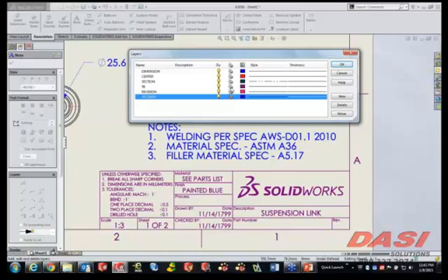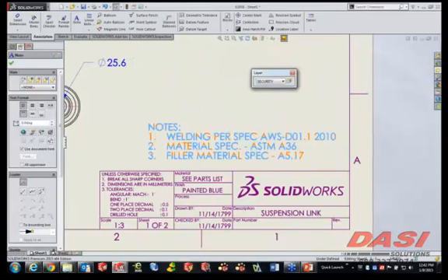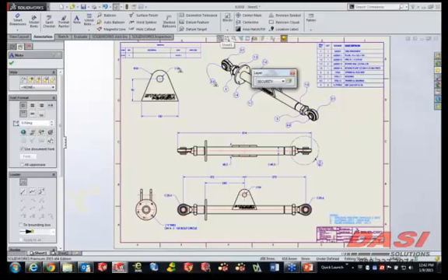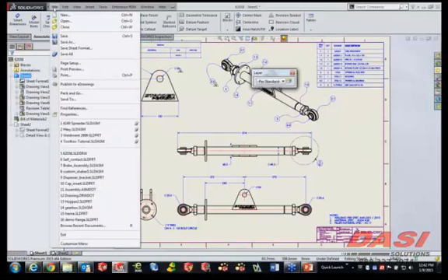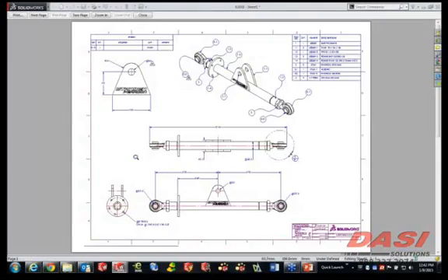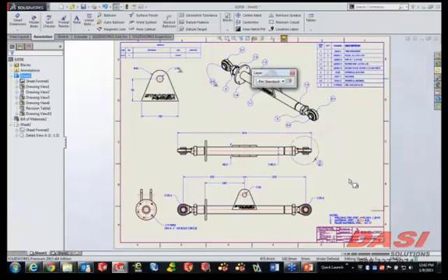So we now have a new column here that allows you to disassociate or disallow any type of layer from printing. So as long as we verify that this particular note is on the security layer, if I was to go ahead and do a simple print preview, you can see that in the print preview that note does get scrubbed away. Now if you print to a PDF, it will also scrub that note away. That's a print operation. It's just to a PDF generator. But if you save to a PDF or save to an e-drawing, it does not apply. So very specifically, that will not print does refer to printing as an operation.